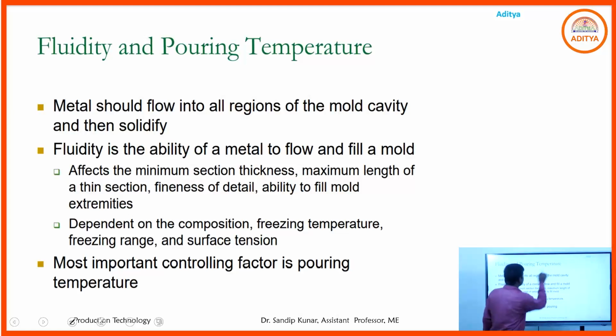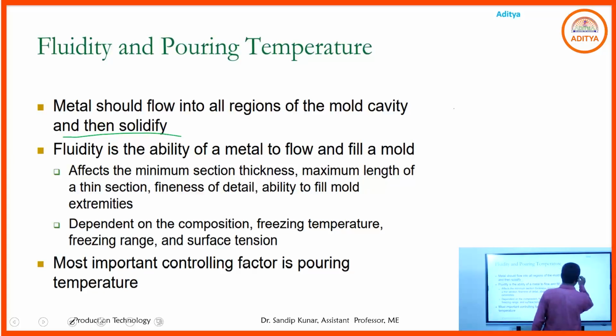Fluidity and pouring temperature: metal should flow into all regions of the mold cavity and then solidify. Every molten material must flow to every space of the mold cavity. If it does not flow to every section of the mold cavity, it will not produce a good quality product.